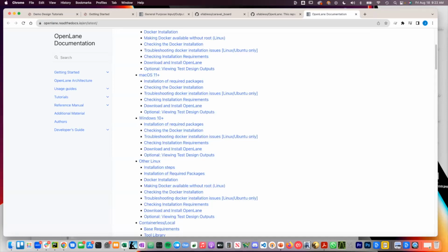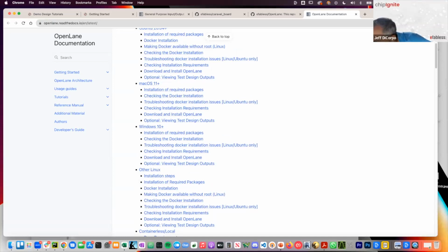Elaborating just a little bit more, you will be able to drive the accelerator, but it won't be super efficient. You can get data to your accelerator, and it'll be more efficient than running the function in software on the CPU. But if you want to run an accelerator with very high efficiency, you're going to want a local memory that you stuff with data, and then you run it in some kind of burst fashion, and then you shut it off. If you're trying to power optimize, you're going to want to localize the data near the accelerator rather than using the CPU to feed it. Okay. So if you have further questions, please post again on that one.